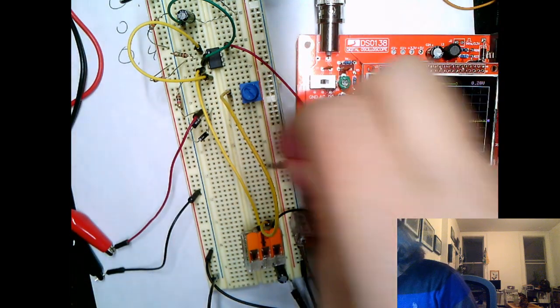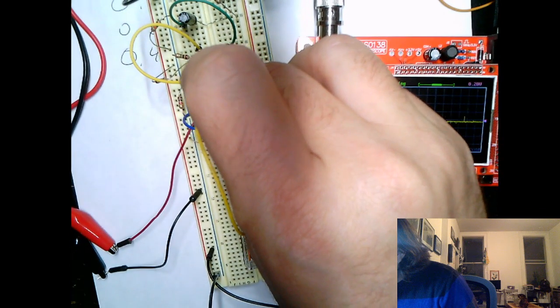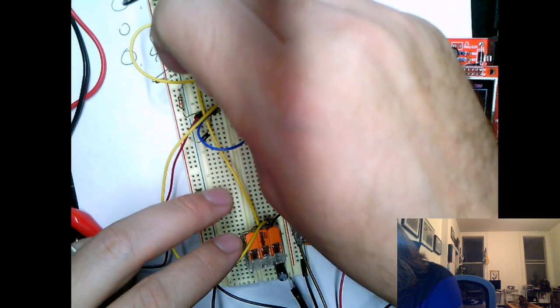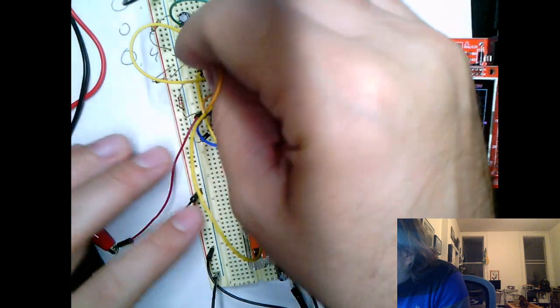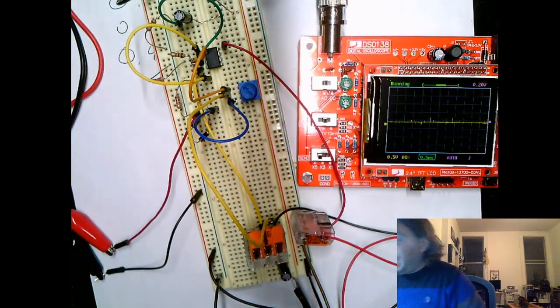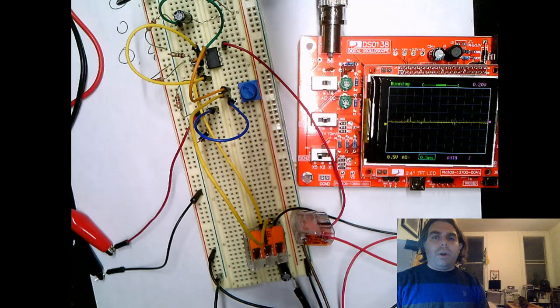And I just have two places, right? Here's my distortion where my diodes are plugged in. I'm going to put that on one side of this pot. And my clean signal is pretty much where my audio is coming in. Now I'm going to pull this from pin 3 of my amp because that's where I'm going into the gain stage. And so let's hear this with a crossfader.